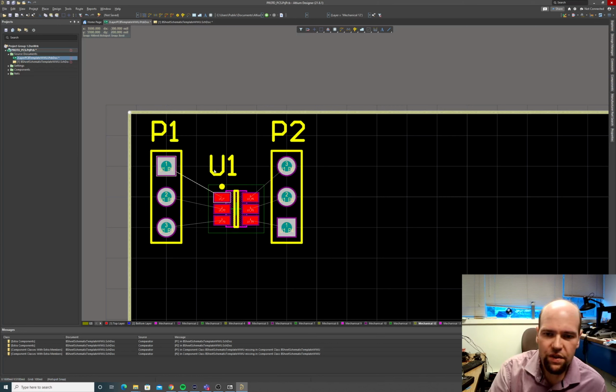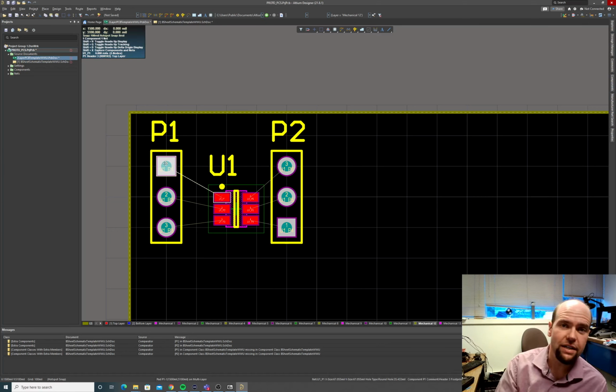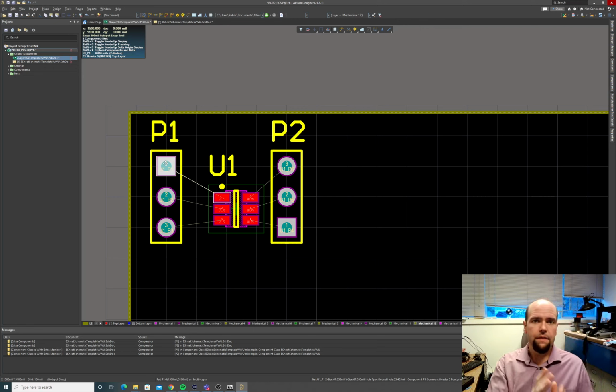So right now, if we click here and then look at our delta X, yeah, we're 400 mil across. So this is further across than a spine. If we used this right now to make a part that was cut out and put on a breadboard, there would be a column of pins that's unused under this part. The hole to hole distance across the spine of a breadboard is 0.3 inches. We're at 0.4, so we'd be jumping over a row. We'd have an extra row.